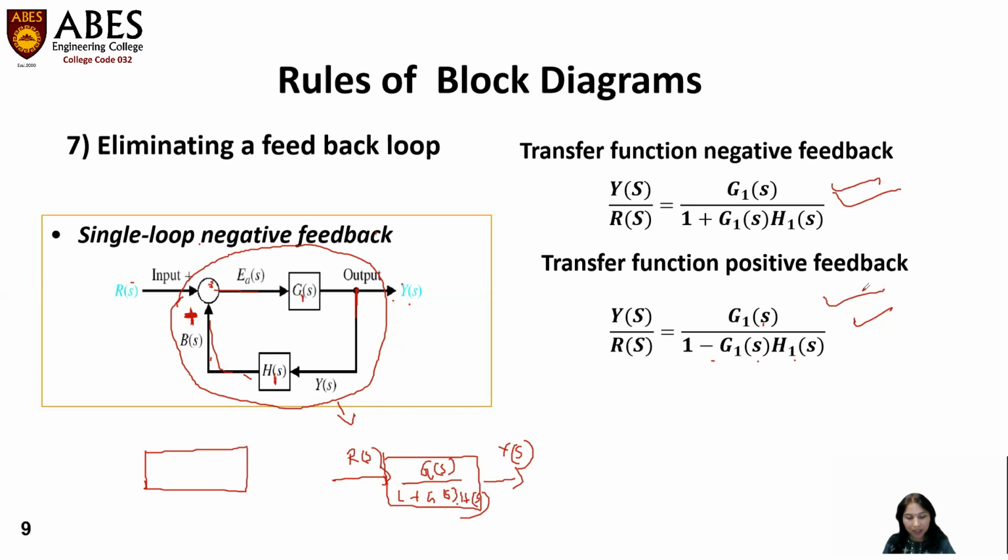So all these things apply while doing reduction of any complex system's block diagram. Suppose a complex system is there and its block diagram is with us; we want to reduce that block diagram using the block diagram reduction technique, and after reduction we will find the transfer function. So basically the main purpose of this reduction is to determine the transfer function.